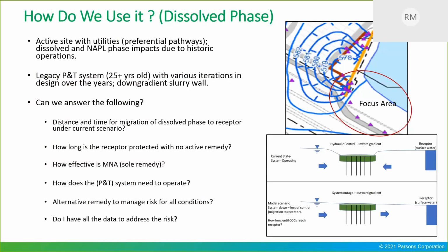So now I'm going to focus more on the case study and site itself. This tool is what we are using as a proof of concept right now. Here you can see the topmost figure is the perimeter system, the current field study location. This is a conventional pump and treat system. Here you can see the red line. They have multiple well point systems for extraction, which is pretty similar to the pump and treat system. And there is also a slurry wall as a second line of defense to stop the migration.